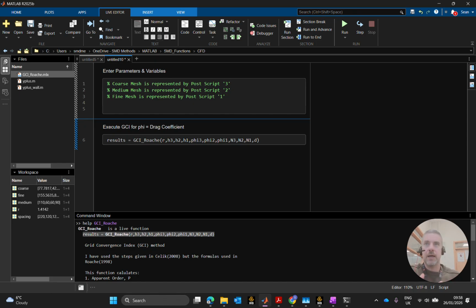What it means there is that most likely our mesh, our discretization, our modeling hasn't been able to calculate that adequately. And one of the ways out of that was obviously to evaluate not only as a spatial analysis, but also as a temporal analysis by using a transient analysis. Okay, so the mesh independence is going to do something very similar here, except it's going to find at what resolution we are able to solve the physics of this flow best.